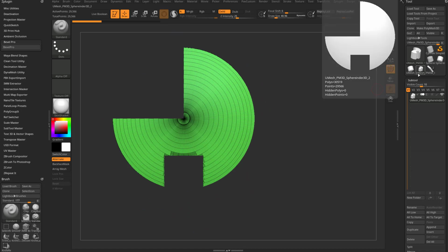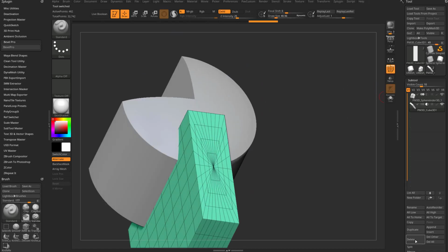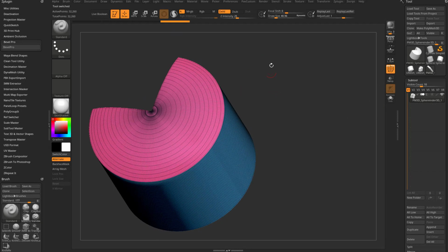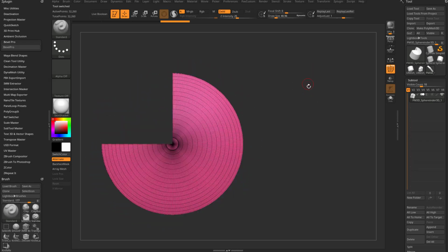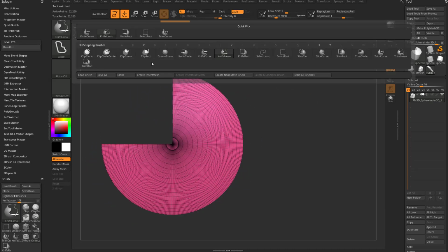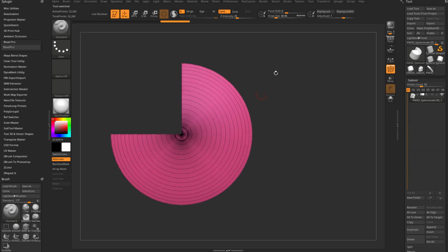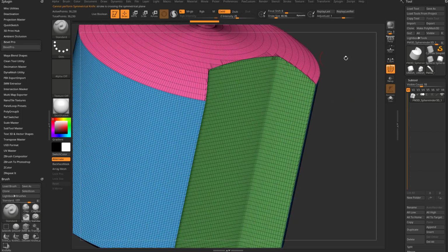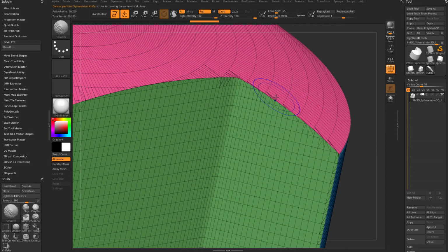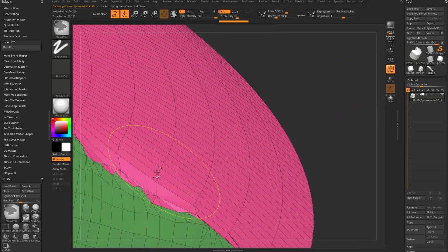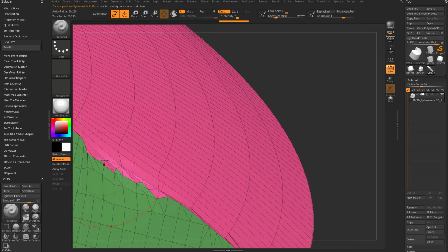In fact, we'll go back to our original mesh here. We'll delete that cube out of our scene. So we have, you know, these polygroups. We already know these polygroups are going to work. However, if we go in here to Control Shift and we grab maybe the knife curve, sometimes these will leave behind some kind of nasty geometry. If you go through here and hold down Shift, you'll see you'll get some overlapping geo kind of in here.